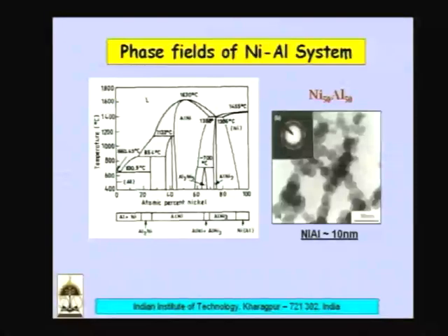So as a result, one can increase the strength of the solid solution by precipitating a larger volume fraction of the precipitate if we can have an extended solubility. Okay. So that's why the extended solubility can give you an improved strengthening, but also can help you in producing these compounds over wide ranges, particularly in case of line compounds where you have a limitation in making.